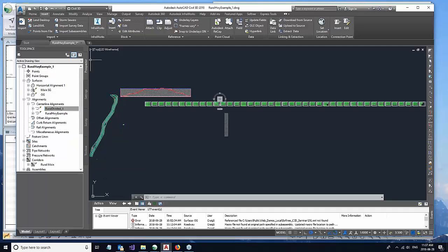So just to re-summarize, we started in Civil 3D with a design file, something that was supposedly completed. We brought it over to Softree Optimal. We set it up there. We approximated the cross sections. We did that pretty quickly. We then tried a few different optimizations of that to compare costs with the original.